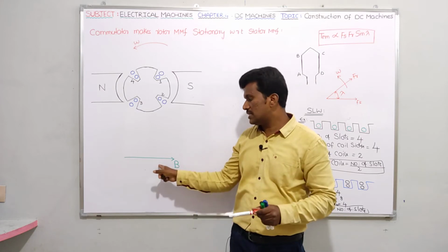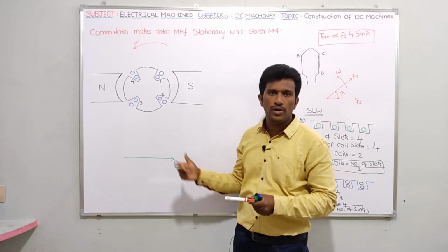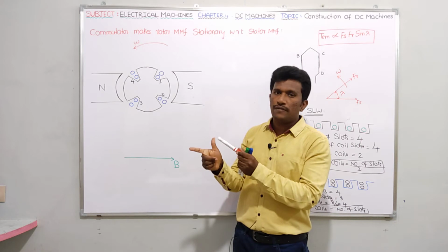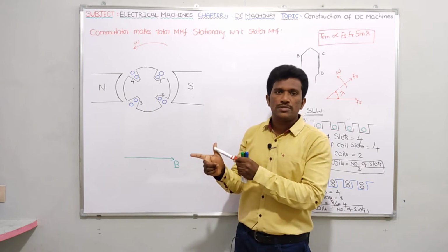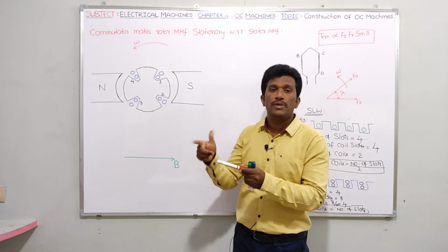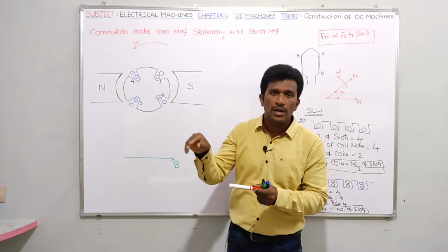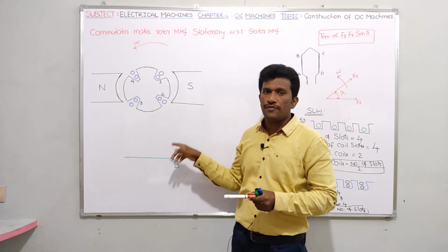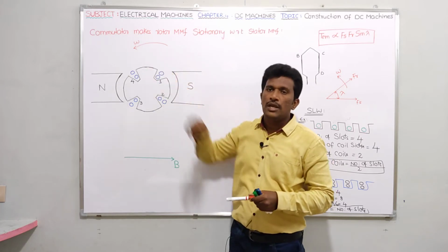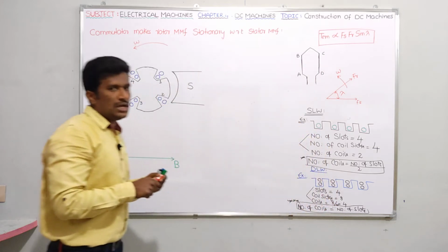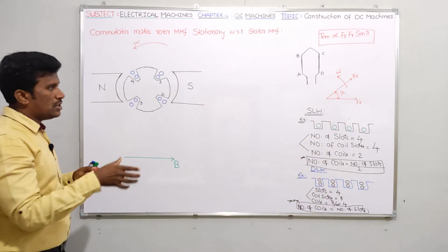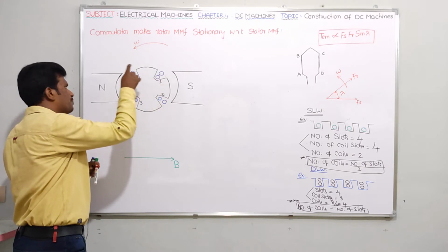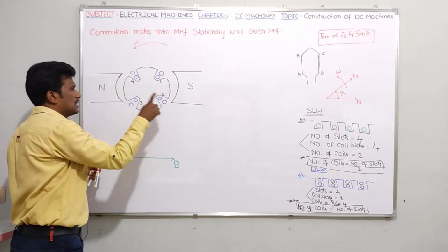Forefinger means this arrow mark, the direction of magnetic field, which we already got. And you should know the direction of thumb, which is the direction of motion of the armature winding placed in the rotor. What direction of rotation of the rotor had we taken? Anti-clockwise. Please take the tangential direction of motion of the conductor at slot 1, slot 4, slot 3, slot 2.